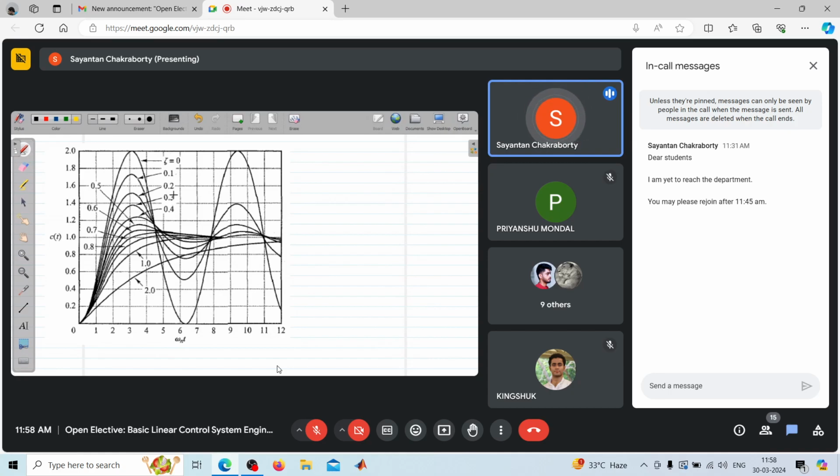If it is say a magic ball or a stumper ball, it will have two or three oscillations like this. If it is a solid deuce ball, then it might have a zeta equal to 1, right, to settle down. Or if it is a very heavy gym ball, full of sand, then it might have a response like this, an overdamped response.